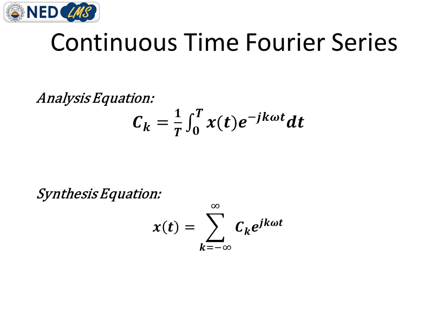And if we are dealing with discrete values, then we use the summation sign rather than the integral sign. So in the analysis equation, these two things represent that you are dealing with the continuous time Fourier series. Continuity is represented by this integral sign, and series is represented by this time period. And e raised to power minus j k omega t is actually the basis function.